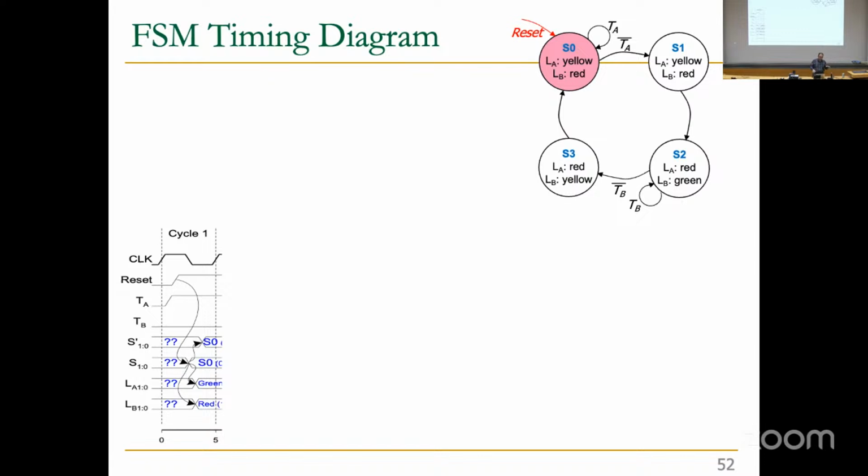That's usually the case for many of our circuits today, because the reset signal comes with a lot of priority and sometimes with safety reasons. Whenever people want to reset, they don't want to wait for even a few nanoseconds or less. They just want to immediately reset the system. That's why people usually use asynchronous reset. We're going to see how we can make asynchronous reset in Verilog today and next week, but this is something to prepare your mind for.